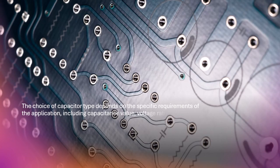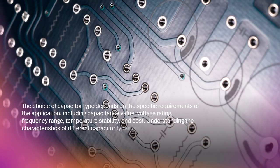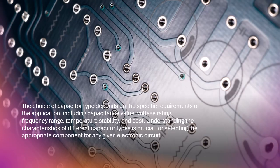Conclusion. The choice of capacitor type depends on the specific requirements of the application, including capacitance value, voltage rating, frequency range, temperature stability, and cost. Understanding the characteristics of different capacitor types is crucial for selecting the appropriate component for any given electronic circuit.